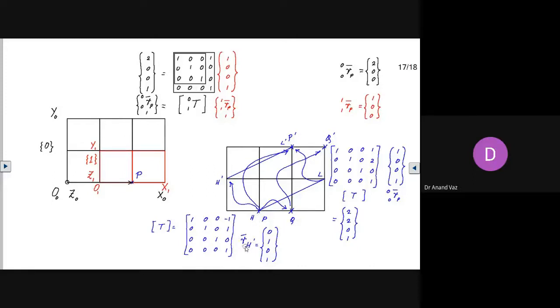So this is one way of looking at the transformation matrix. The second way, of course, is well known to you. It indicates the location of one frame with respect to the other. So we can use the transformation matrix for two ways. One is to translate vectors, and secondly also to specify the position or the location of one frame with respect to another frame. So it can be viewed in two distinct ways.